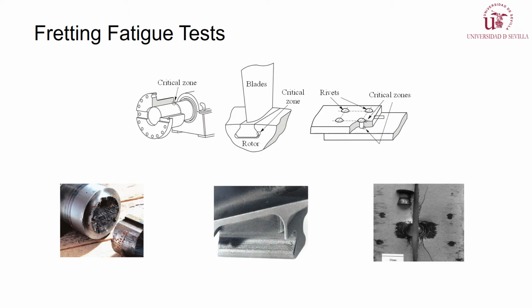Fretting fatigue is very often material damage in mechanical contacts. This surface damage is caused by small oscillatory displacements, which are the consequence of friction between mating surfaces, and small surface cracks appear at the contact zones. These cracks can grow until the complete fracture of the component.